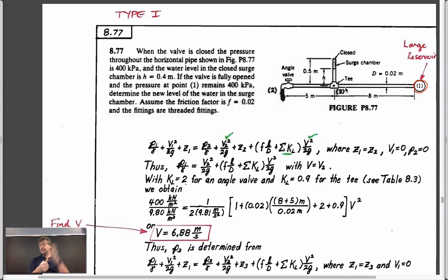And so what you have is when you shut the gates, there's a surge tower, which is typically, if it's in a hillside, it's either outside the hillside or it's actually tunneled as a vertical shaft in the hillside. The water stops against the gate, and instead of everything stopping, the stuff upstream piles up and just raises the elevation in the surge tower, surge shaft. And sometimes that surge shaft is closed, and so there's an air cushion that develops with pressure, which kind of cushions the blow. Sometimes it might be open, which just allows it to come up to its natural height.